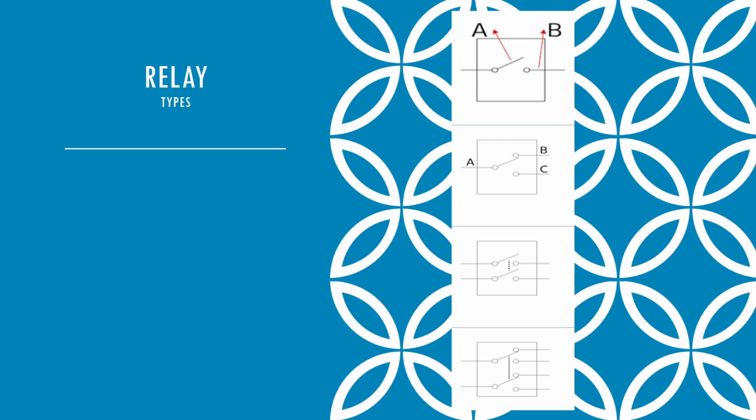And the last one is double pole, double throw. It's basically just two of the top ones on the same board, but you can use it to reverse polarities for a motor, or handle logic for multiple lights. I've mostly just used these to save space.